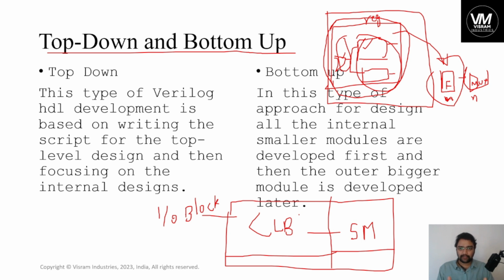If you write module codes for the logic cells and you take care of input and output wires and how they are connected, take this information of the internal elements and come to the top level design where some other elements like flip-flops or multiplexers are connected. Write the HDL module code for each cell and connect these input and output wires according to those multiplexers. Like Y is the output for this AND gate,